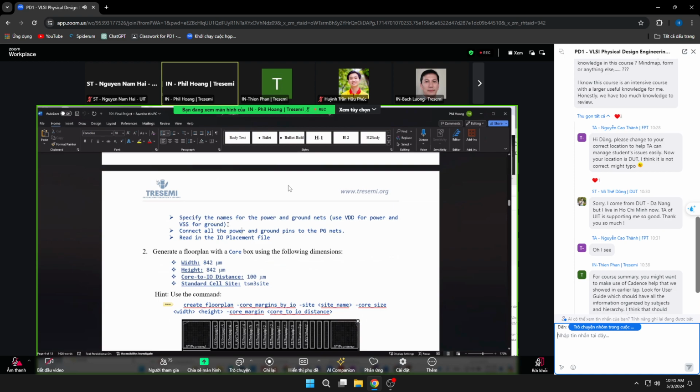In the netlist coming from synthesis, these are logical. So there's no power and ground, which are physical. Power and ground don't exist in the logical view. So you will need to tell the tool what the nets are. These are the net names that you connect all the pins of the cells to. The macro cells have power and ground pins.